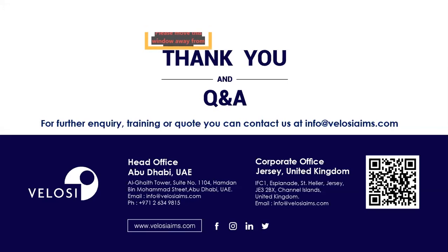In the event of exceedance like PM10, what will be the course of action to mitigate this emission? Well, basically, it depends on the nature of why it is an exceedance. On that basis, we can propose some mitigation measures. For example, if it is during the construction stage, and we feel that it is due to vehicular movement, then we can propose that the roads should be paved, and we can also propose that water sprinkling should be used so that the dust can settle and not disperse, so that the particulate matter emission does not exceed limits.